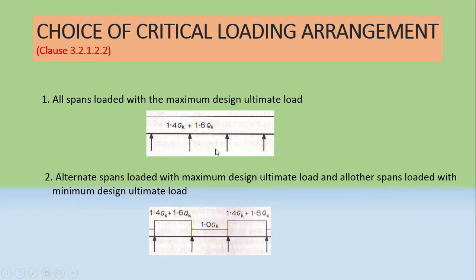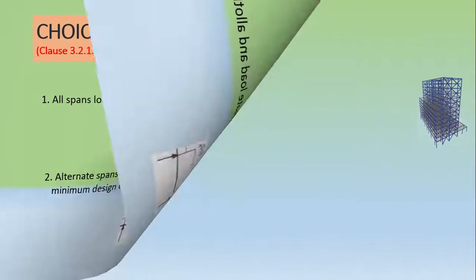Then according to the bending moment diagrams which have been drawn for these two cases, you can calculate the maximum bending moment at mid span and the maximum bending moment at this support. According to that you have to design. Please remember, you can learn easily if you are watching this lecture series continuously.